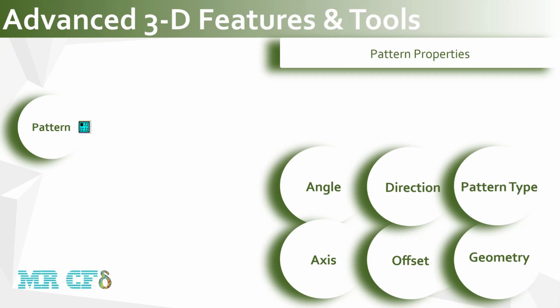If the value of this property is 0, then ANSYS Design Modeler will automatically calculate the angle necessary to evenly space the patterns about the rotation axis, and you will see evenly spaced indicated in the property instead of a numerical value. The default value for angle is 0.